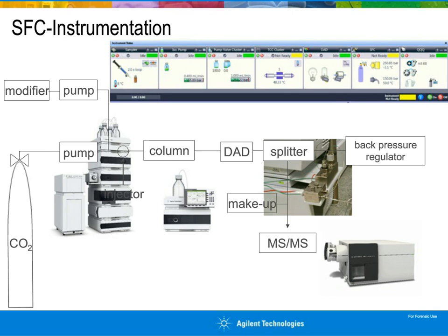What you see on top in that little graph is the instrument control. This is MassHunter, as this is running on a triple quad instrument, and you can see basically every single module from any of those stacks being represented here, which means in day-to-day routine operation this is very easy going. The method has been set up, and all aspects are stored and loaded together with the parameter file